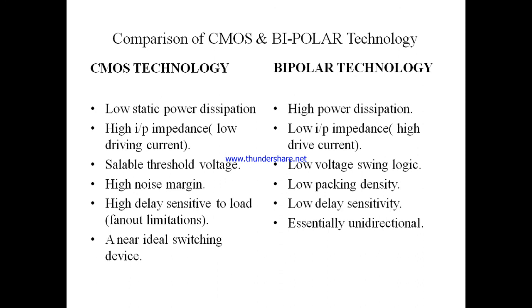Bipolar technology has high power dissipation, low input impedance, that is high driving current, low voltage swing logic, low packing density, low delay sensitivity, and is essentially unidirectional.